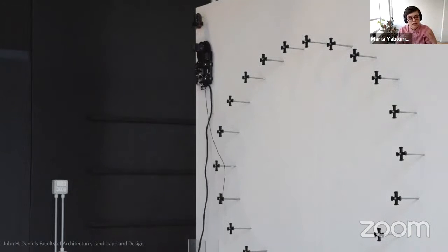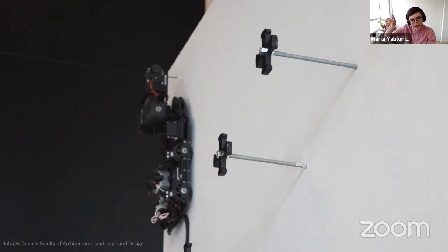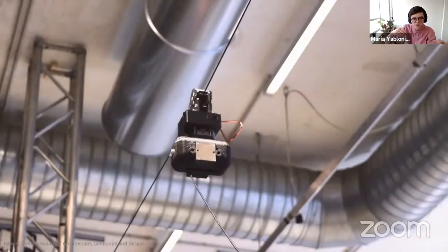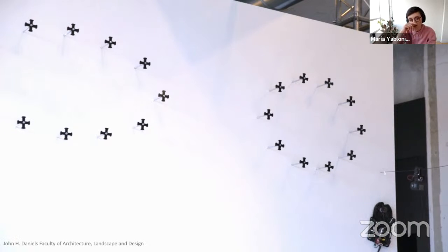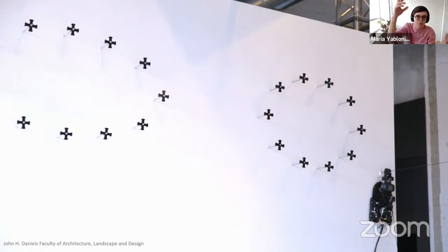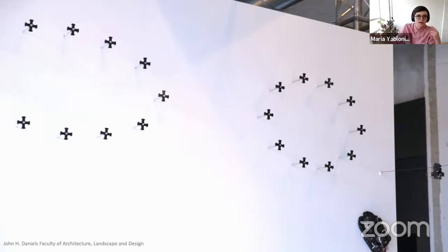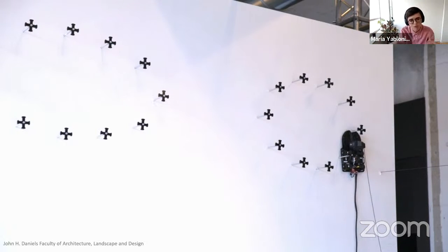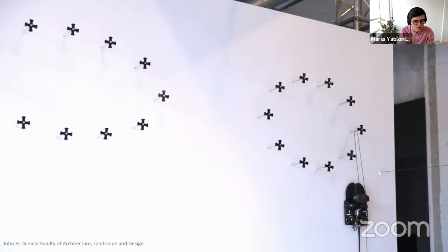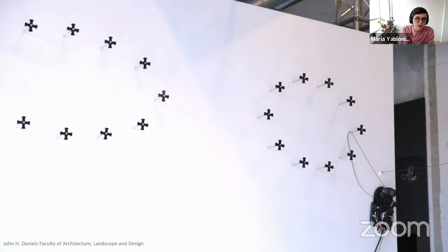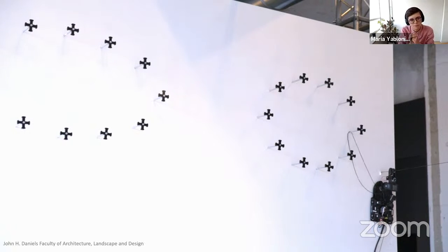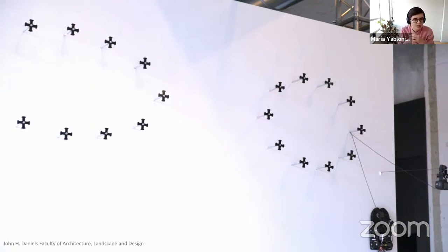The wall climber, which has a special end effector that allows it to anchor filament around these pre-installed anchors, goes and finds the correct anchor in a sequence of anchors, does the whole anchoring routine or the connecting routine, comes back to the shuttle, and passes the bobbin back to the shuttle. Then, through iteratively performing these same three operations of anchoring, passing, and then moving from one wall to the other, the overall system can produce a pretty extensive tensile filament structure using some of the principles of cordless filament winding.